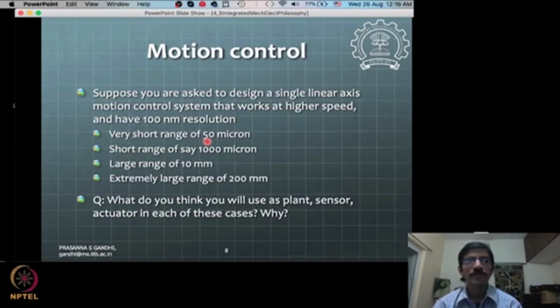So the way the piezos are moved, the motion takes place in that fashion, and then one can enhance the range of piezo actuators. People have designed actuators like that using these inchworm motors. That's what they call it, based on the worm-like motion. The same principle is used, biomimicking the similar principle, so those are used for enhancing the range with piezos.